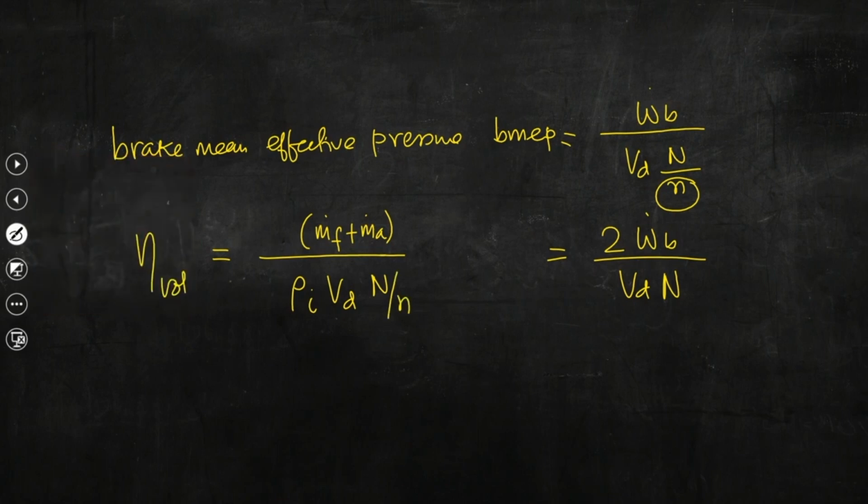So, you can understand that we are supplying the amount of air during the intake stroke, of course, per cycle. There are 2 revolutions per cycle. So per cycle, this is the amount of air that is drawn into the cylinder. Now, the issue is that we need to supply m dot f plus m dot a, that is the total charge.